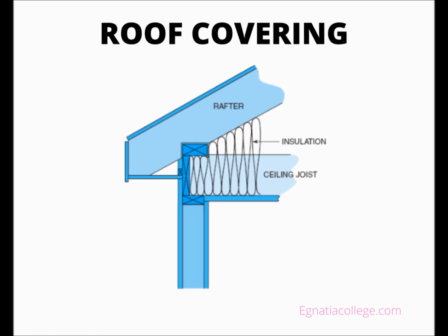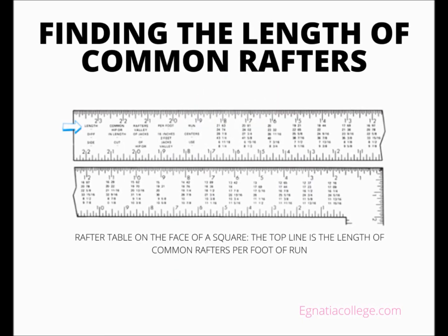Raised heel rafters and trusses can be used to make more room for insulation and proper ventilation at the edge of the roof. In raised heel rafter construction, the ceiling joists rest on the top plate with a joist header capping their ends. A separate plate is nailed on top of the joists and header, so the bird's mouth of the rafters rests on this upper plate. In this way, the full depth of the joist is available for insulation right up to the edge of the roof.